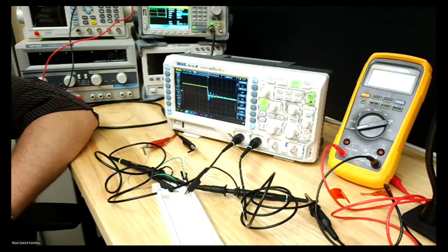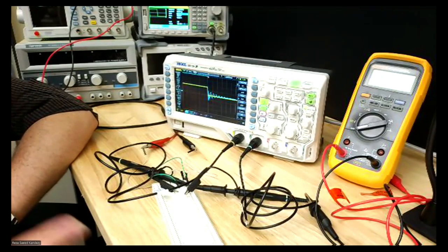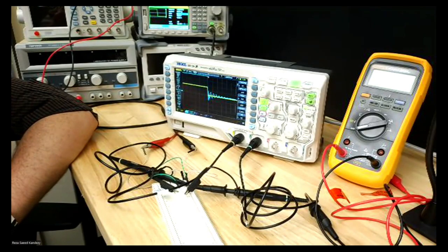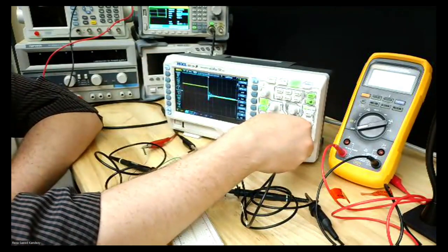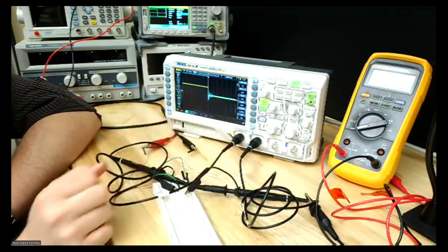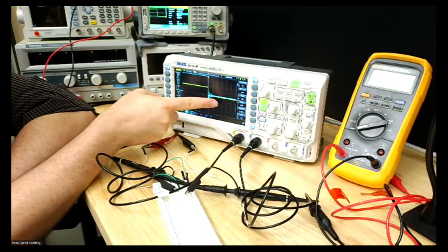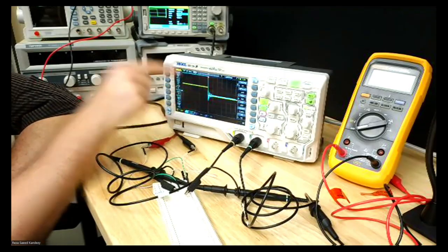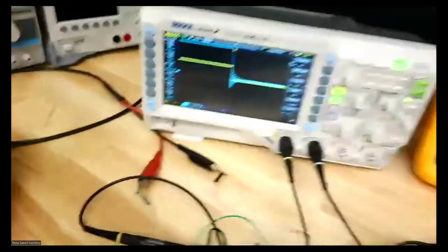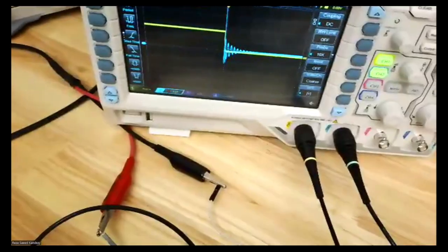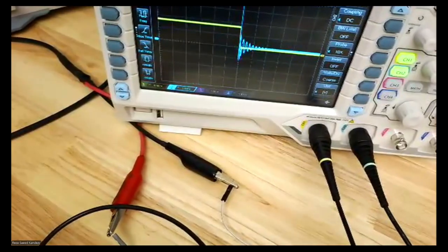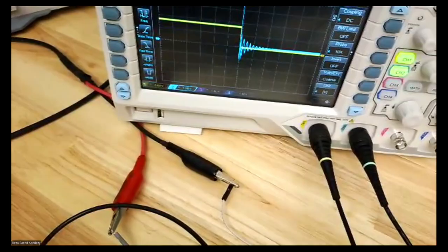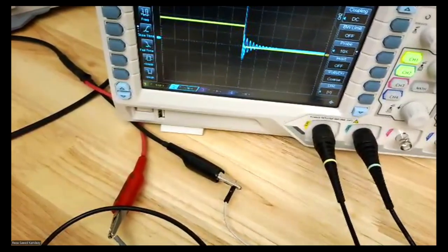Now, the time that we define is from when the input signal gets disconnected and goes to 0, that edge, until we stabilize at the 0 line. If you look at it, which I hope is clear, it takes 2 of those squares until we get to a certain tolerance, where the error is so small that we can say we are now settling at 0.